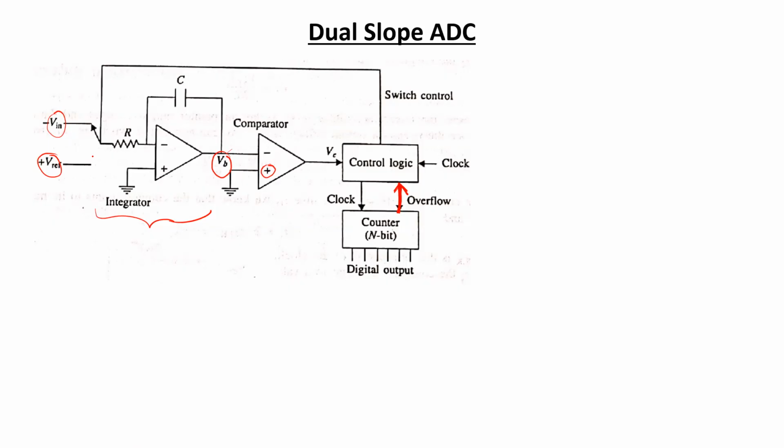Now, to elaborate a little bit more about the operating principle, like I said, the circuit will start its operation by integrating the input voltage first. But how long is the input voltage going to be integrated? It is going to be integrated until the counter has finished counting up to its maximum limit once.